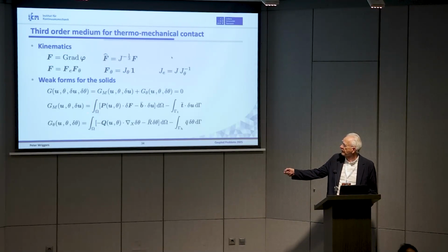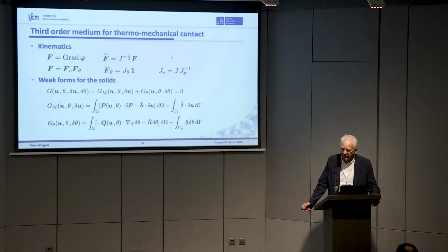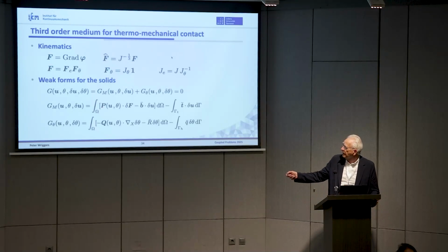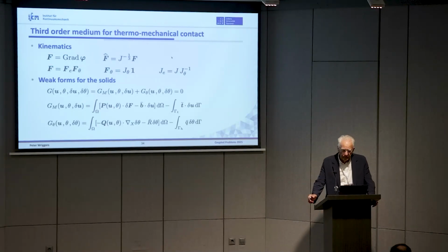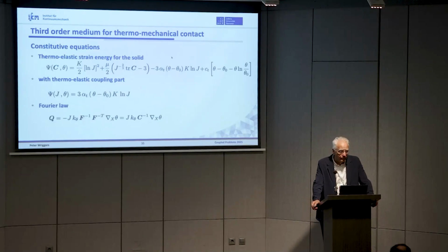For the weak form for the solids, you have the one which is classically given, and then you have the weak form which governs the thermal heat conduction. In this case, I have only looked at stationary processes. The pressure, the first Piola-Kirchhoff tensor, of course, depends on U and theta, and also the heat flux vector depends on the deformation, as we will see in a moment, for large deformations.